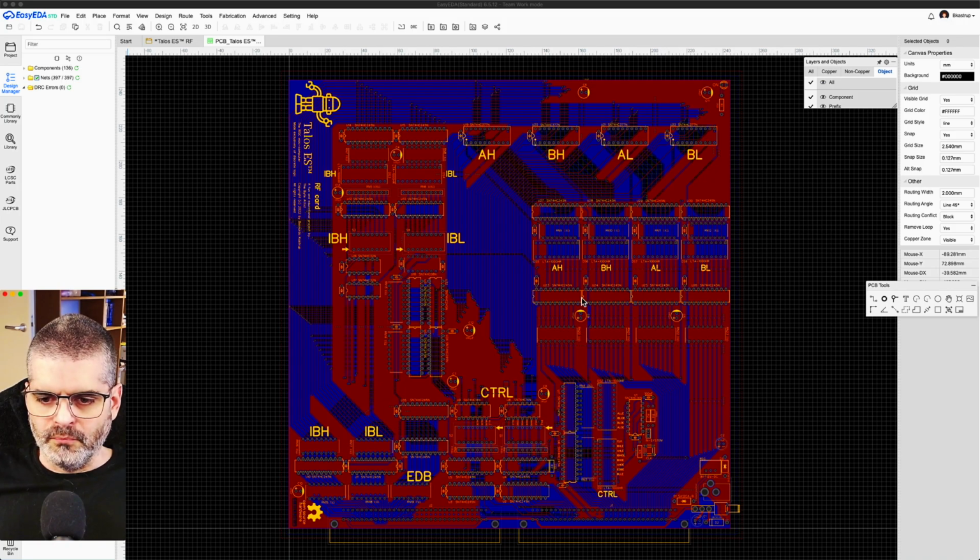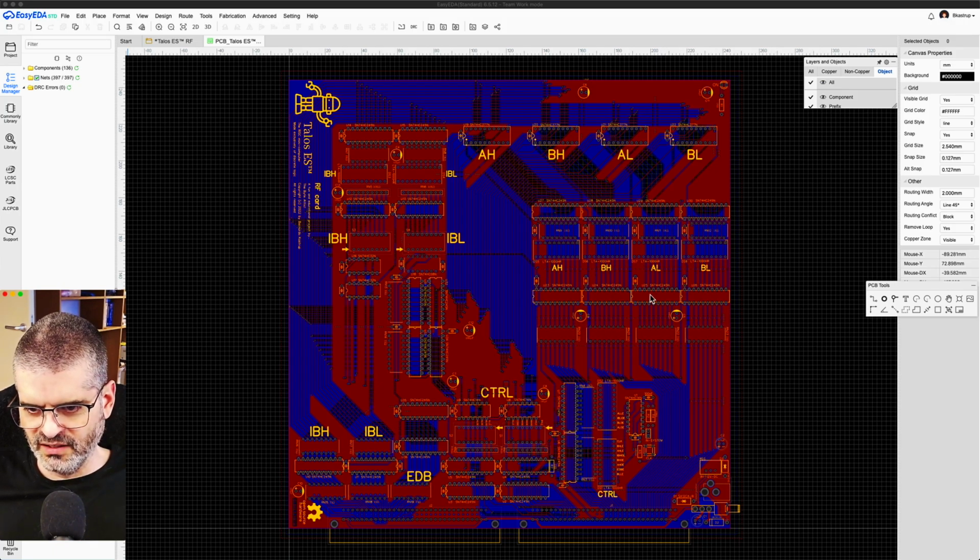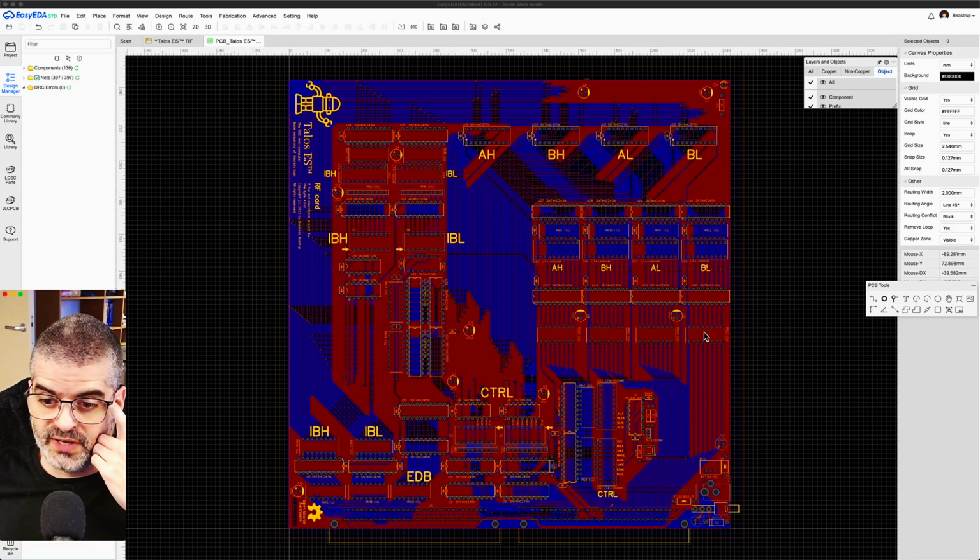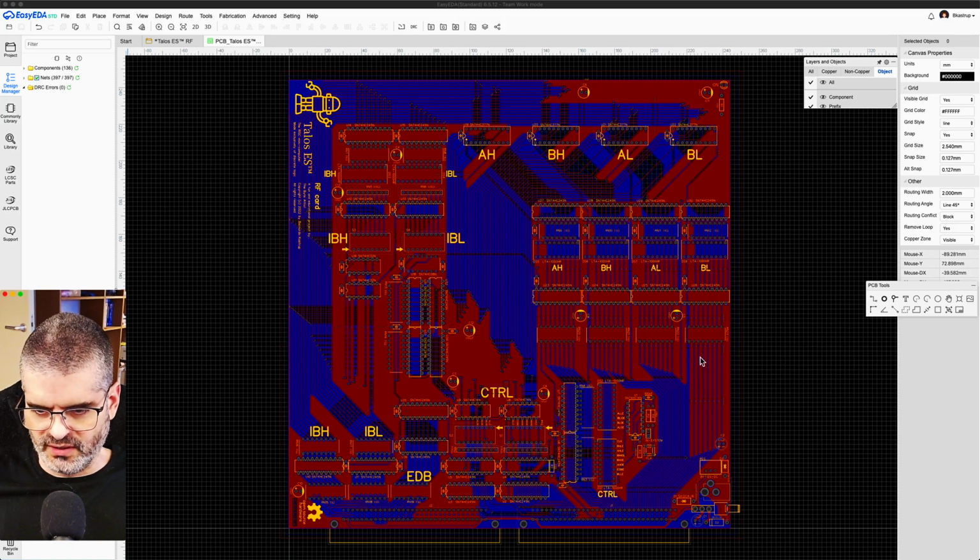Then there are more buffers, 4 dedicated buffers with 33 ohm resistor networks connected to the outputs, driving the lines that go to the ALU card. So the contents of all 4 registers bypass the internal bus and go straight to the ALU card here via these lines here, here, here, here, and here to the backplane. So I put the 33 ohm resistors there to absorb reflections from the backplane so they don't go across the backplane towards the ALU card.